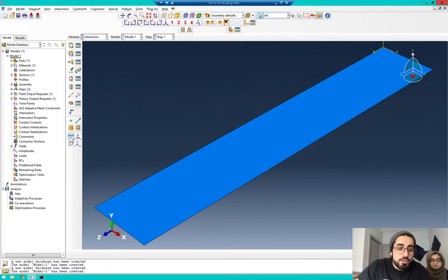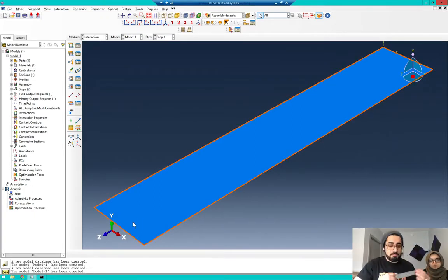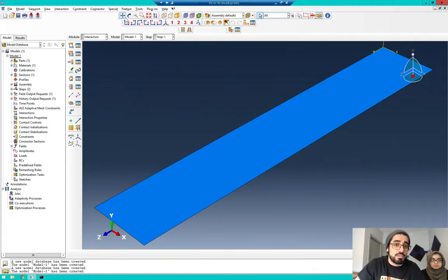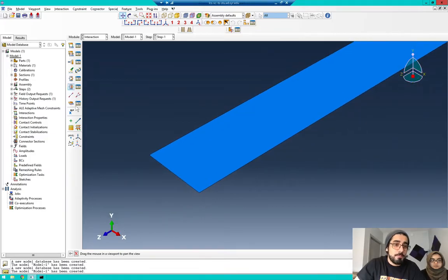Good. So I'm gonna go here. I'm putting the load here, right? So I'm gonna link all of the deflection of all of the points along this width to a point in the middle, okay? Because I'm gonna apply the load here in the middle. So I'm just gonna define a point first, called a reference point. I go here, create reference point to link it to other points. I click here and they tell me, where do you wanna put the reference point? I wanna put it here, in the middle. Good, done, escape, good?